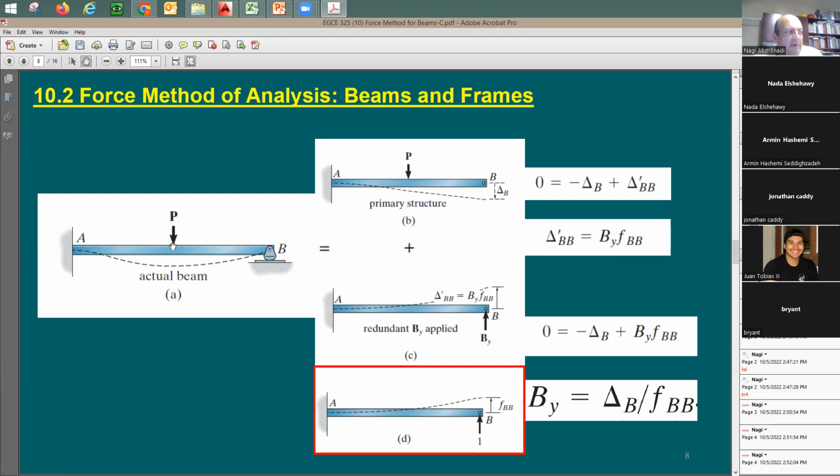This can be my beam, right? The beam is given to me like this. It has a point load, with the length and all the information, EI and the point load. I'm trying to solve it to find the reactions, but I cannot, because I have only 3 equations and 4 unknowns. So there is no way for me to solve it the easy way.